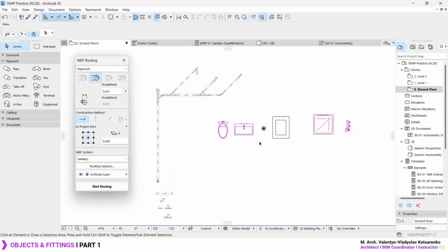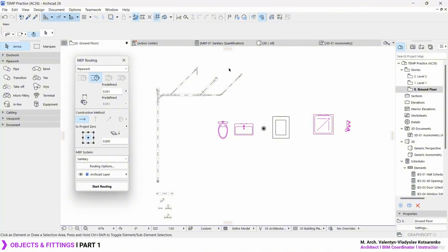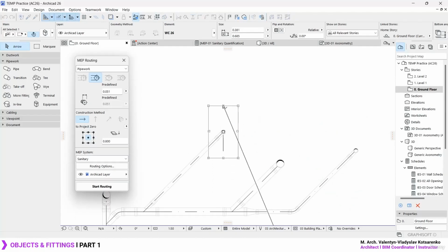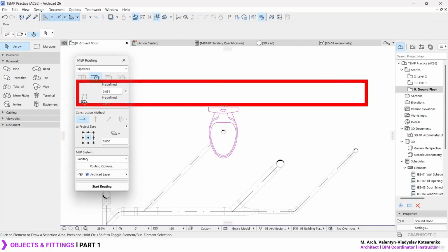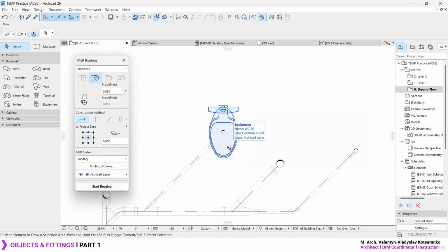Okay, so we got pretty much everything ready. Now let's start positioning the objects and work on the connections. First things first, let's see where we can position this object. In a real workflow, you will always have walls. In first place, you will have the object. So this is something to keep in mind. It's not first the installation and then the objects, but the other way around. You first place the objects in an architectural distribution and then you work on your facility. So make sure that the branch is always defined by the object and not the other way around.